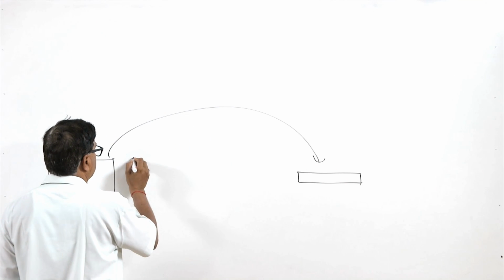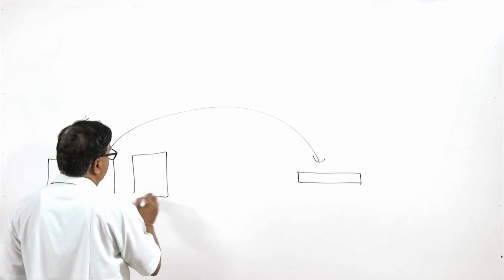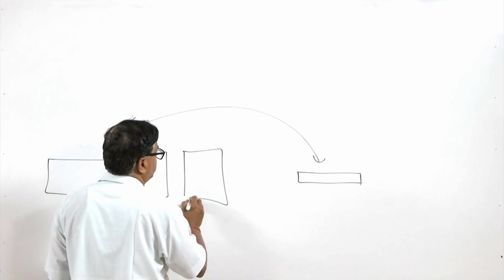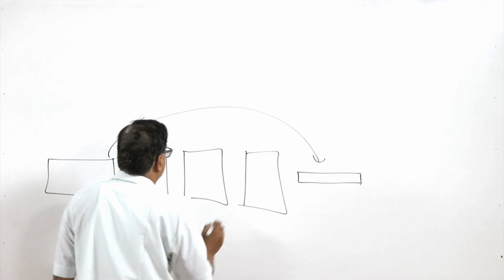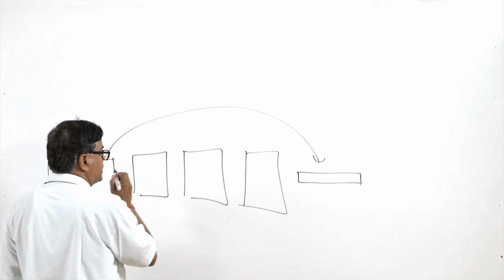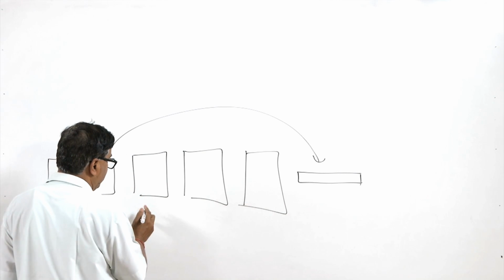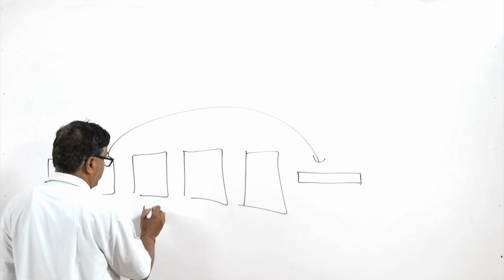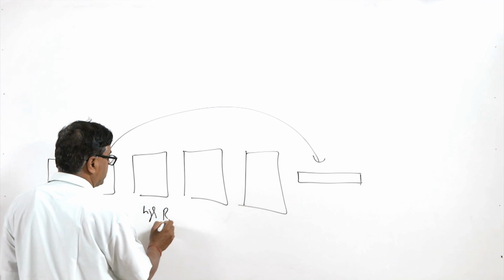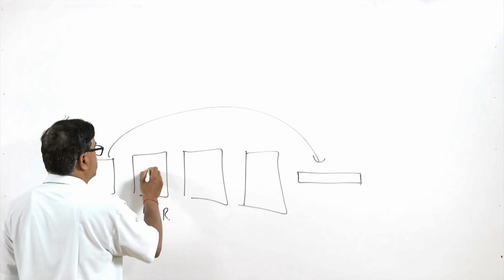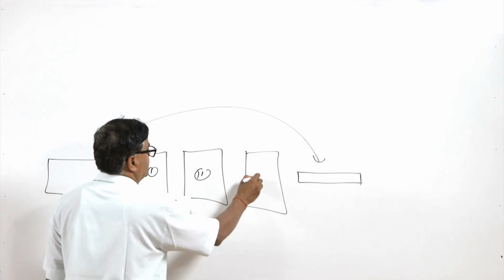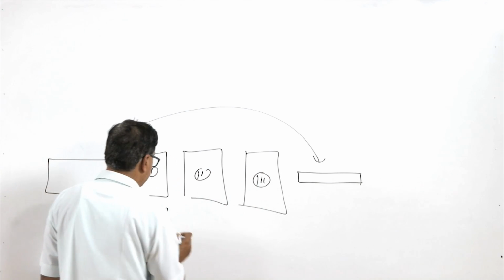In that case there will be a number of dies used, and the wire will be drawn sequentially, with somewhat higher reduction percentage at stage 1, then stage 2, stage 3.